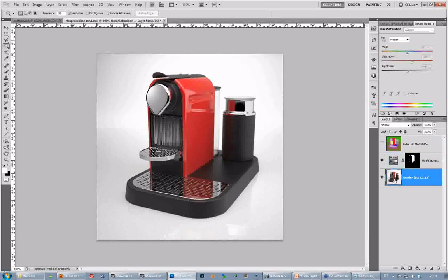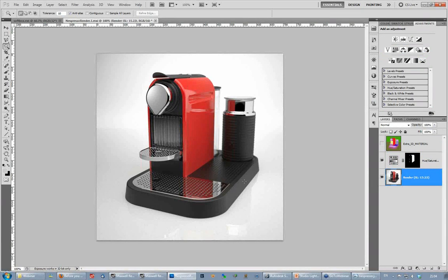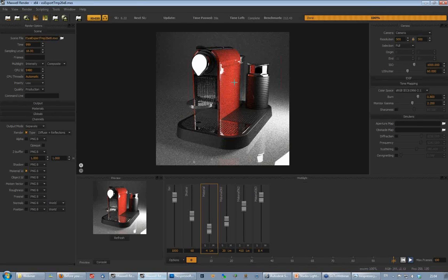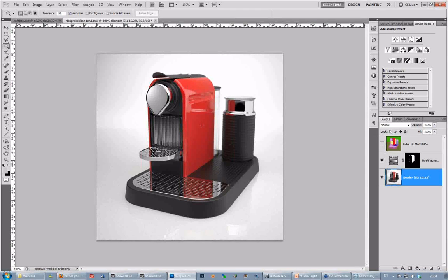Finally, another important thing to keep in mind when you open the MXI or when you're dealing with any rendered image in Maxwell is that when it's rendering, it saves the image in something called linear space, meaning that there is no contrast adjustment, or no tone mapping.